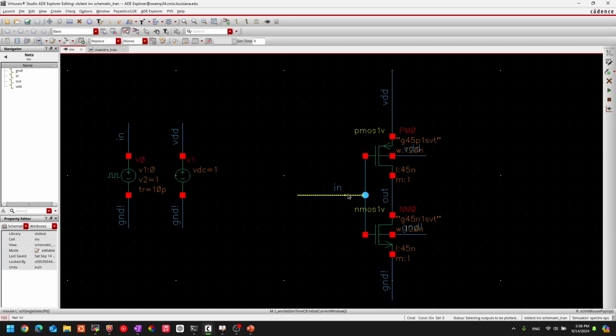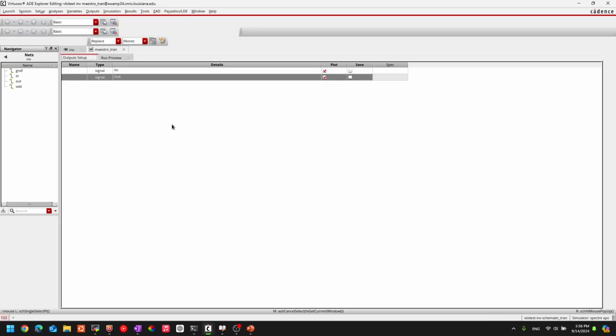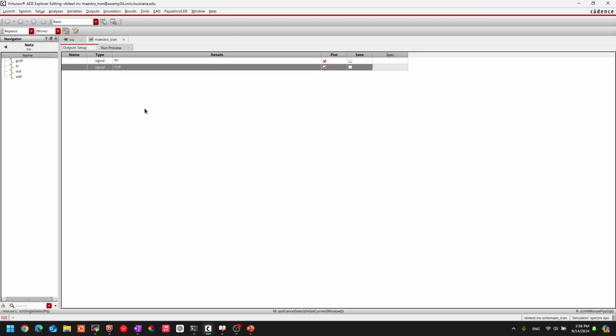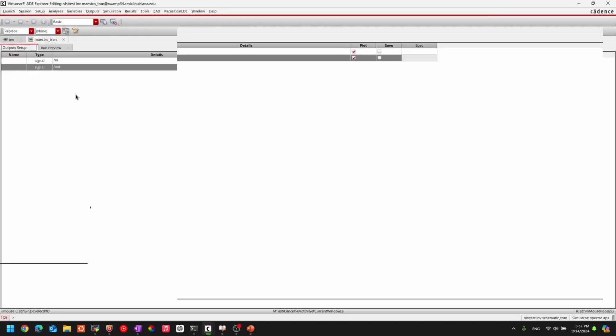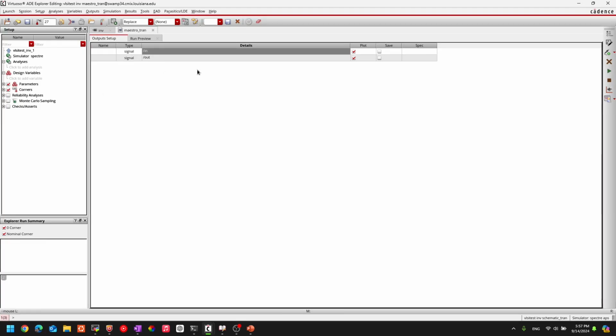All right, click on in and then click on out. And that's about it. You don't need to plot anything else. And then press escape, and then navigate back to Maestro_Tran. So now you've got both of these signals. All you have to do is click on save.